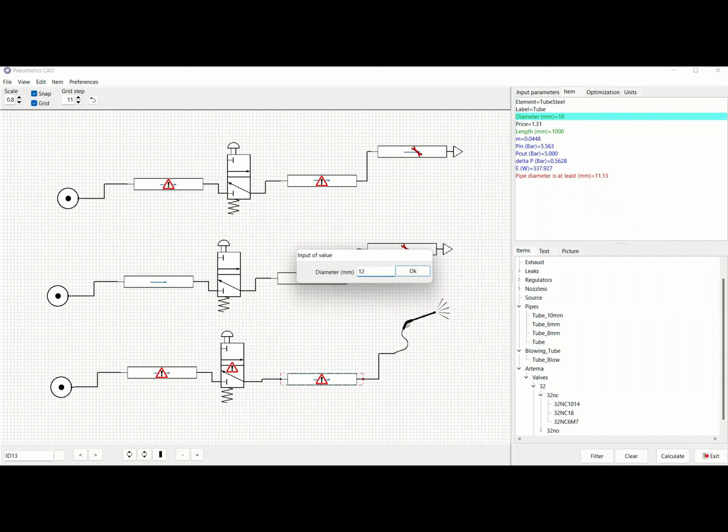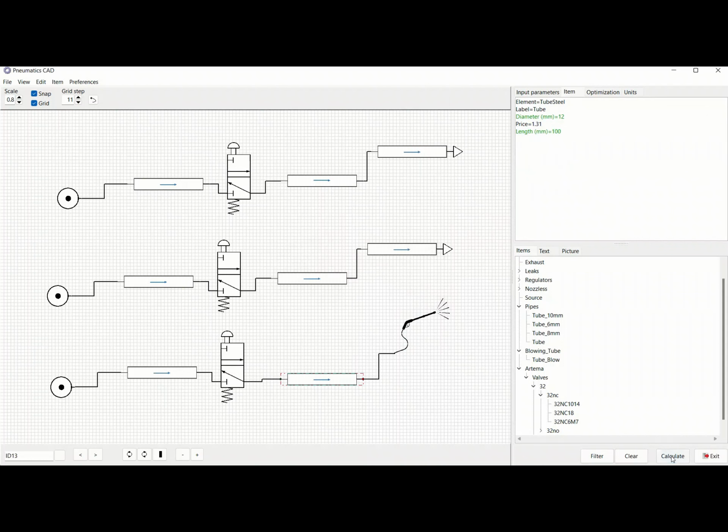And we see, so before changing completely all the components, we need to calculate always step by step, because the previous pressure drop has an impact on the next one. So now we have the lower pressure drop. However, we still can change it. Maybe we can play also with the length. And right now, here, for example, the pressure drop is already lower. The same principle we can also do with the pipe diameter here. And as you can see, the costs are already lower.